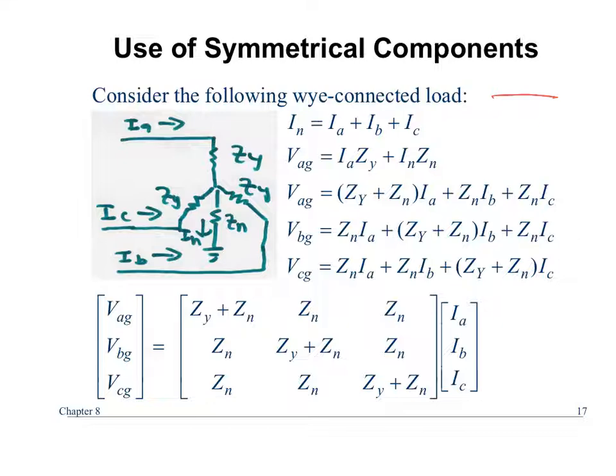This is how we've done everything before, right? We've done single line or one phase analysis, haven't we? If we have three phases and they're not balanced, is this voltage to ground the same as this voltage? Or this voltage? They are not the same. So that whole approach about doing single phase analysis, wave bye-bye, because you can't do it anymore, right? Doing single phase analysis is much easier for us to do on paper. So if we do symmetrical components, we can do everything as a single phase representation.